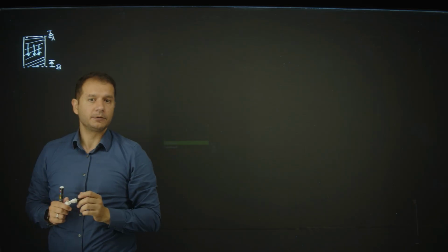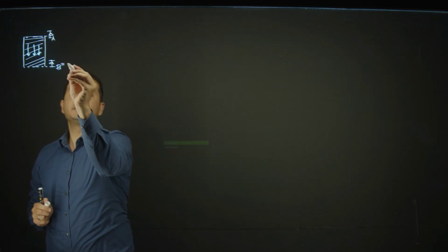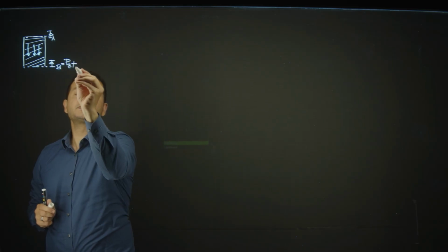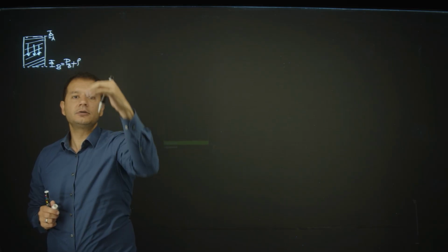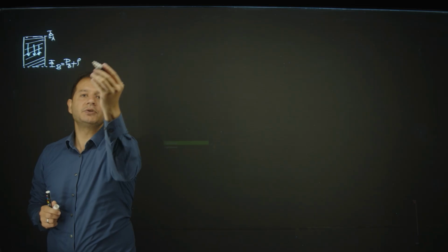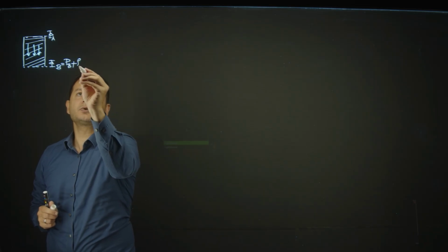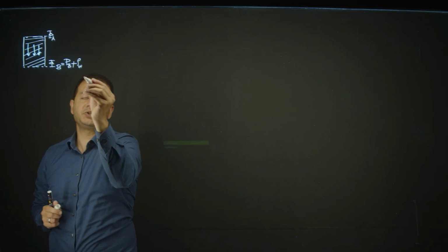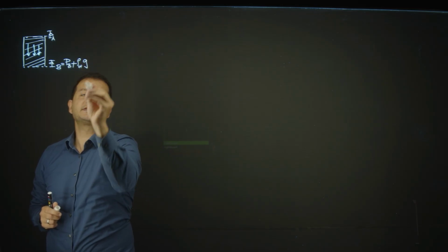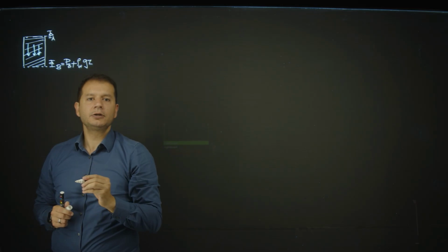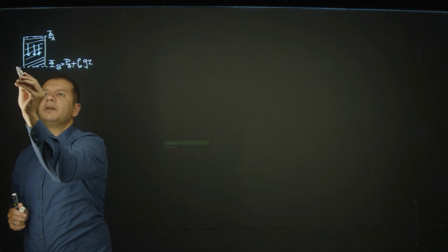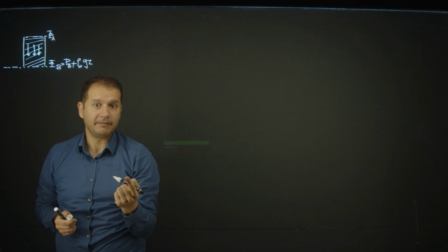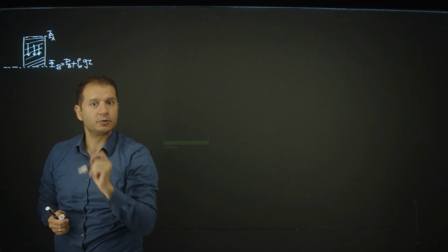What's the potential? Potential is the thermodynamic pressure at the point plus the gravitational effect, which is the potential, also called. So density of water, if my fluid is water, which is the case, gravitational acceleration, and elevation from a reference level. Any level, doesn't matter, because the difference matters for the flow, not the absolute value.